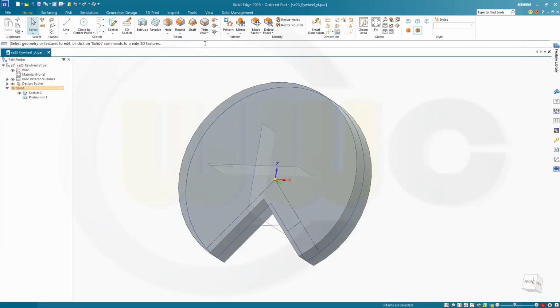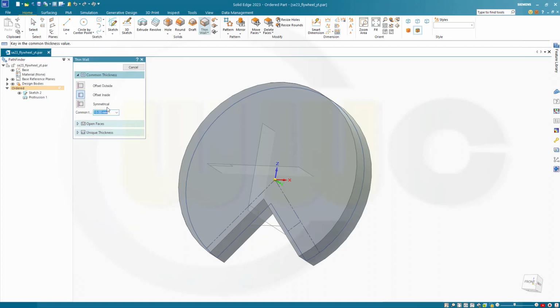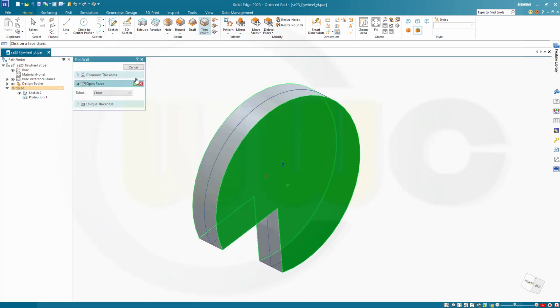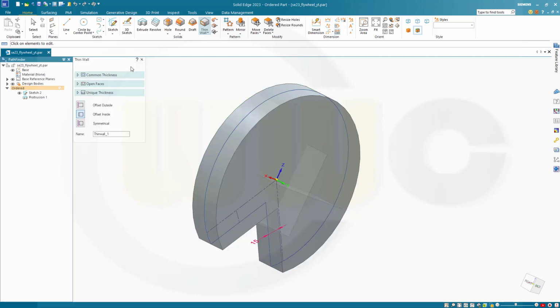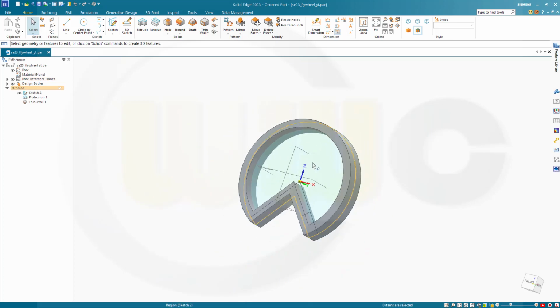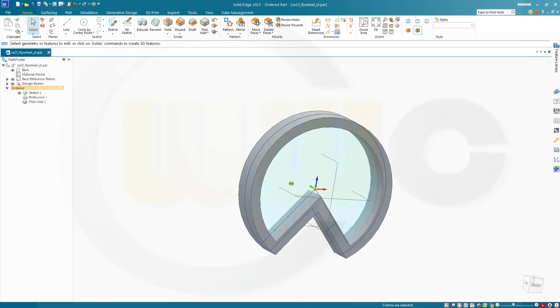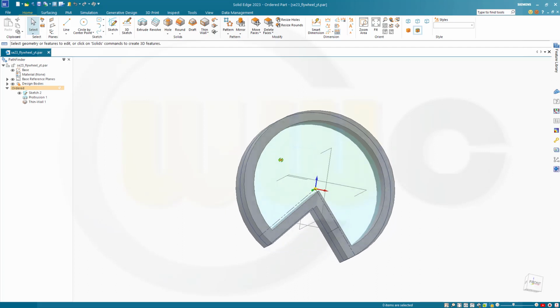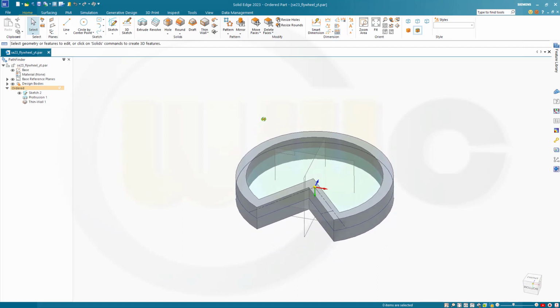Okay, let's go for a thin wall. It should go to the inside, yes, 50 millimeter, yes, and I want to remove this face and that face. And confirm, preview, finish, no cancelling out. That's interesting. Now, there are some limitations in SolidEdge, so how to proceed?